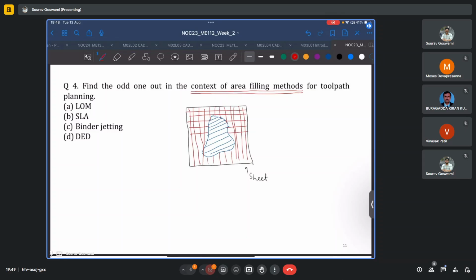And using a suitable laser or a knife, depending on the type of feedstock material, we will then eliminate all of these unwanted regions. Say we can simply run the laser or knife along these grid paths, which will end up eliminating this unwanted material in the form of small cubes.